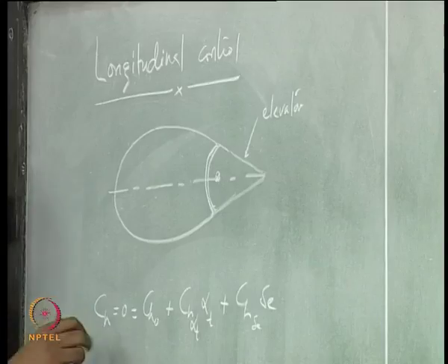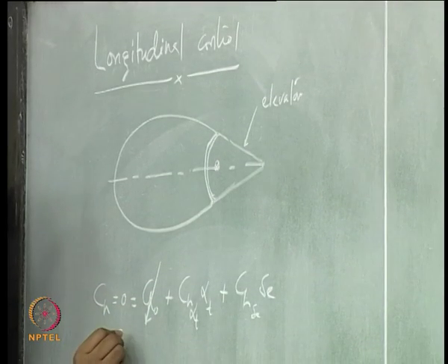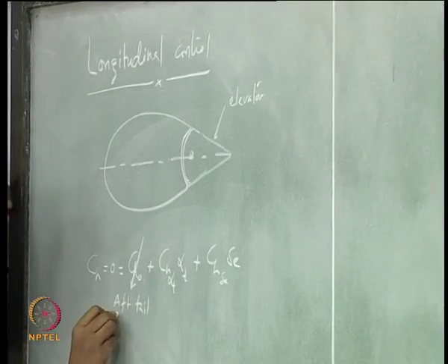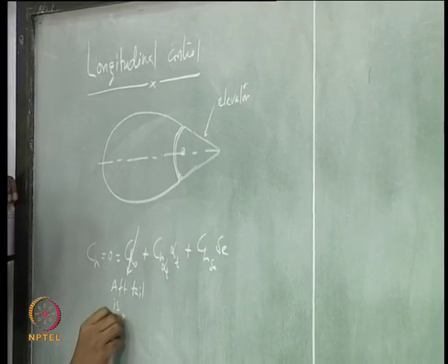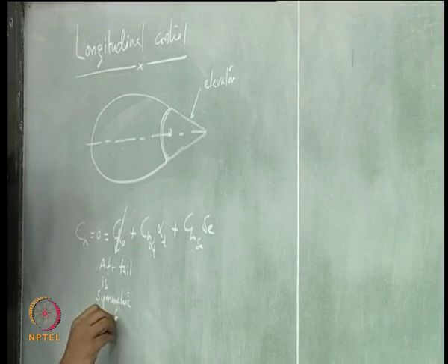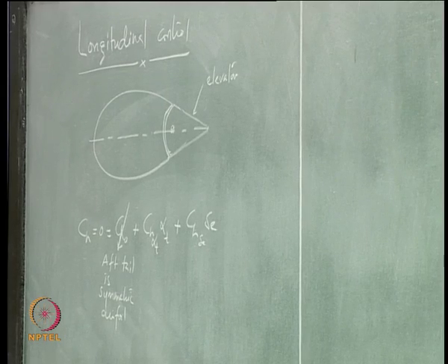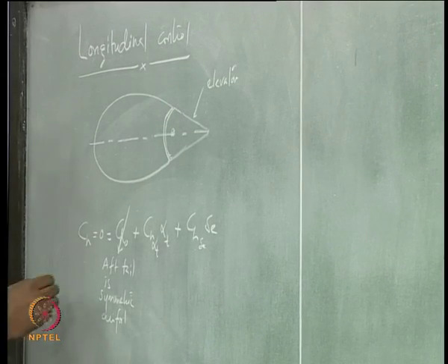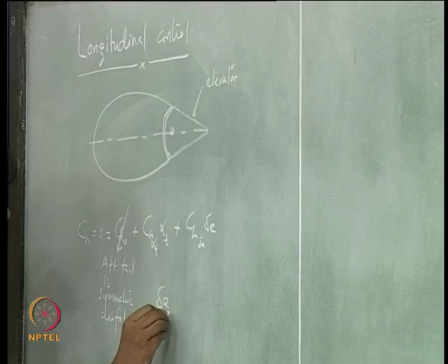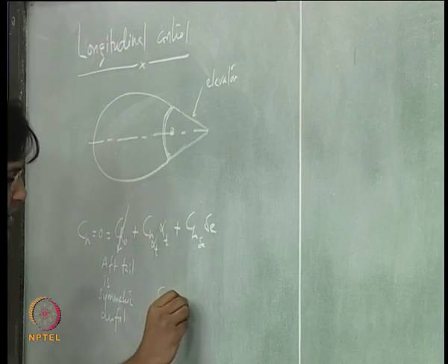So, there this CH naught term may not be 0. Right. So, when I set this hinge moment to 0 and assume that the aft tail is made of symmetric airfoil sections, then this goes to 0, and we found an expression for delta E free.